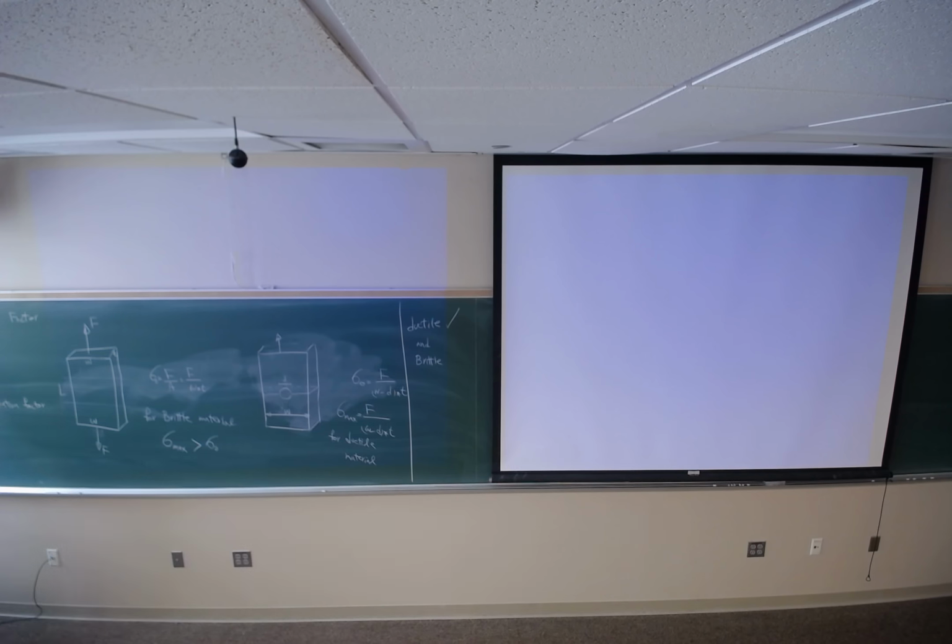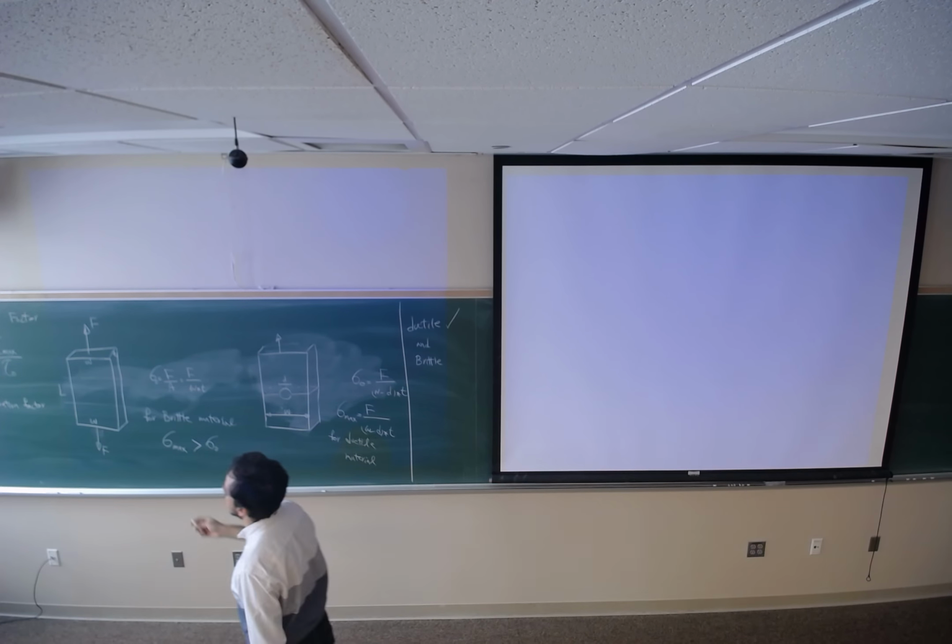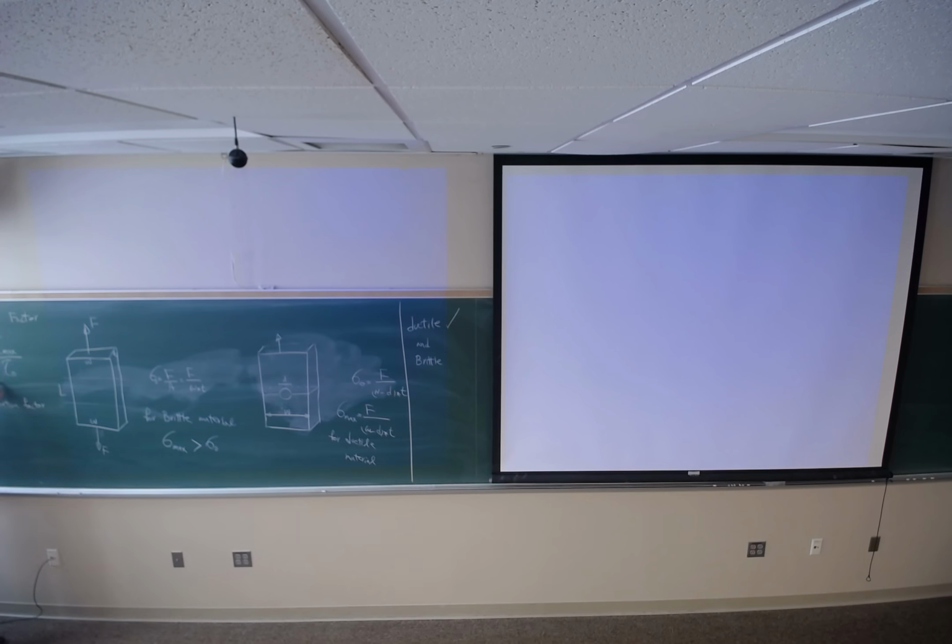So this is for the normal stress. If we are talking about the shear stress and the ratio of the actual maximum shear stress and nominal shear stress, then KT is going to be represented by KTS, which is the shear stress concentration factor. So we have KT and KTS to represent the stress concentration factor.